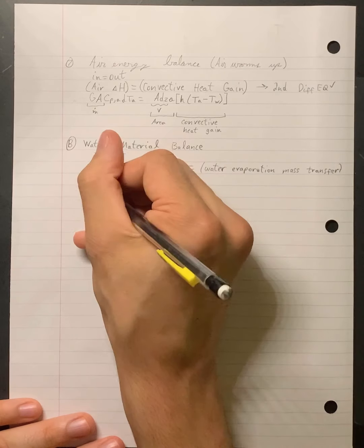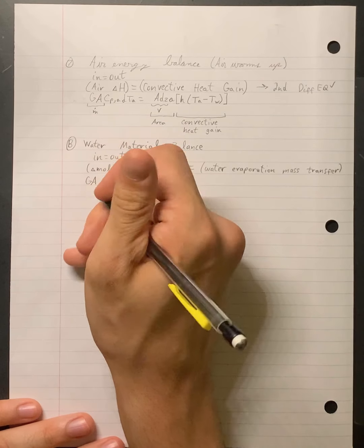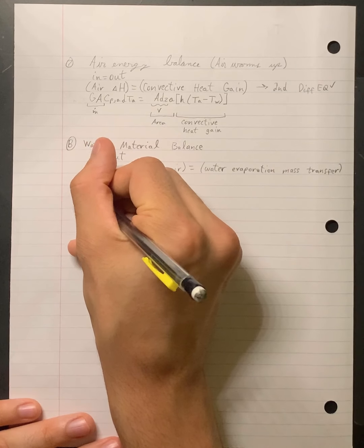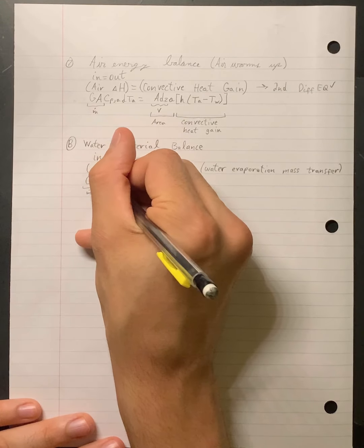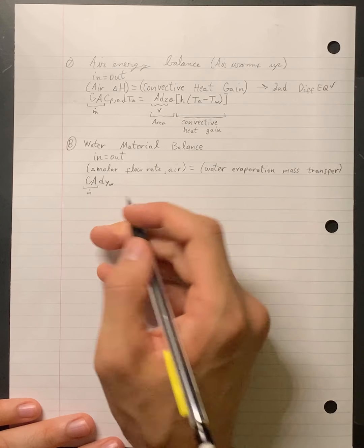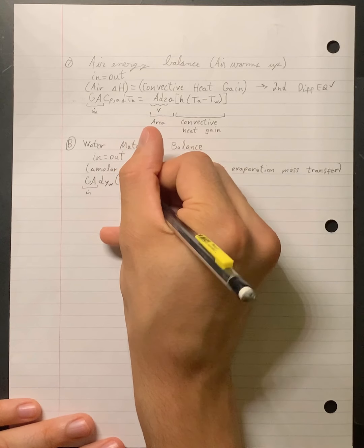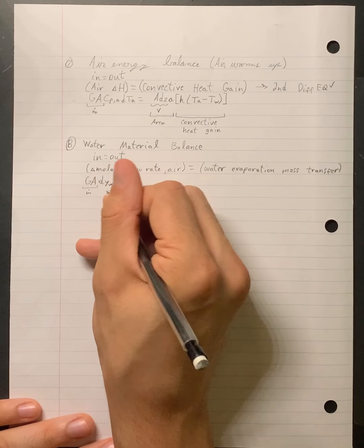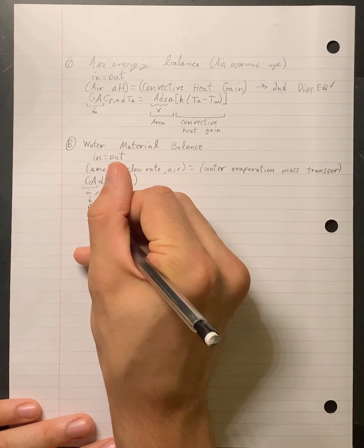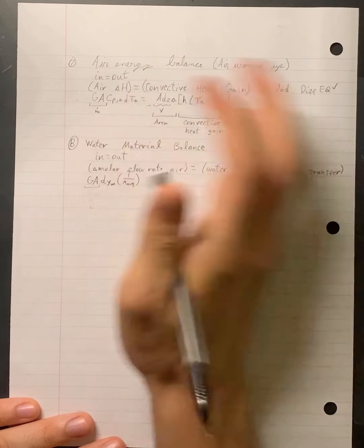So first, again, we've got to write out some form of mass flow rate, which we can do as the overall gaseous flow rate times the area. This gives us a mass flow rate, then times the change in mole fraction of water. Now, with this, we've got a mass flow rate times the differential change in mole fraction. That basically is useless to us. So in order to change that to what we need it to, we just divide by the average molecular weight. So this basically converts that to a molar flow rate and a mole fraction we can work with. That's all that's doing.